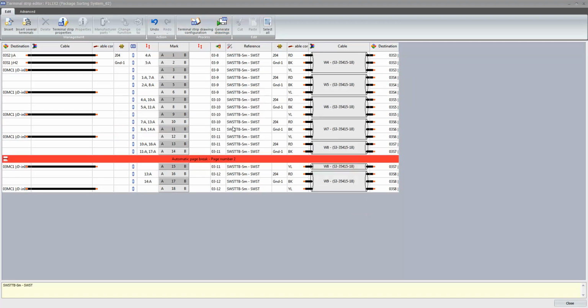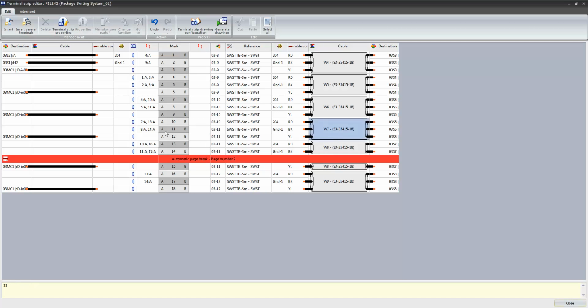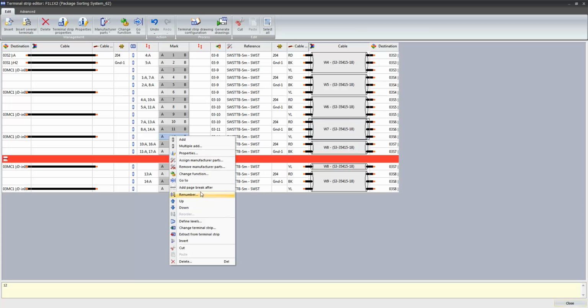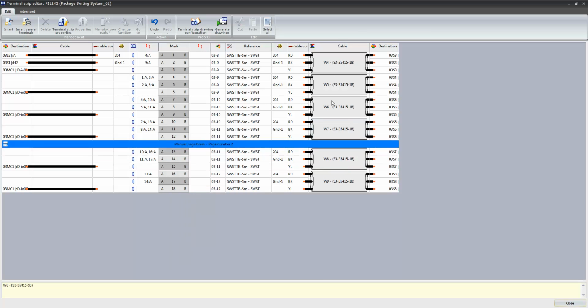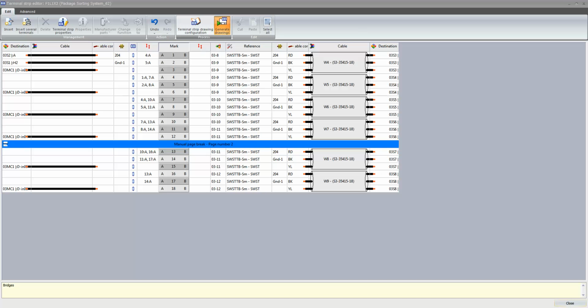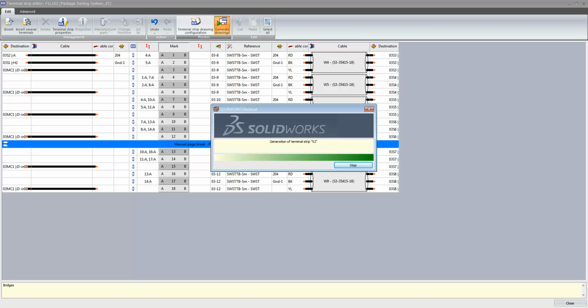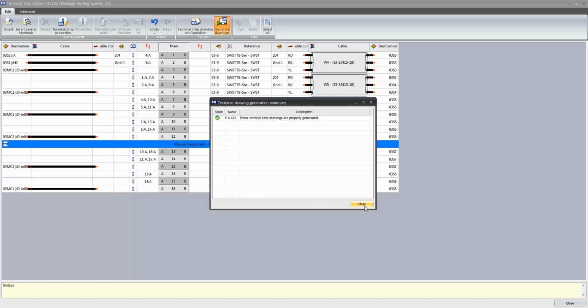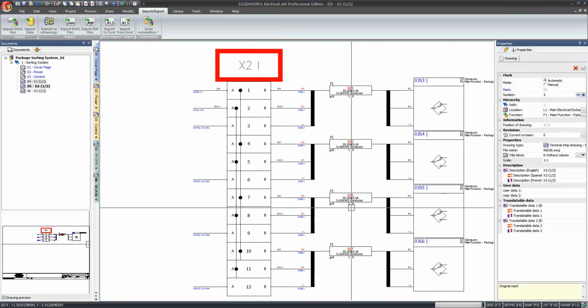And as you can see, because it made everything more compact, I was able to move the automatic page breakdown. But we're splitting a cable with 2 cores on one page, 1 on another. Don't like that, so let's put the break below wire 7 here at terminal 12. That way I can get 4 full cables on one page and 2 on the other. And we'll update that. Hit OK and close. And there's our drawing.